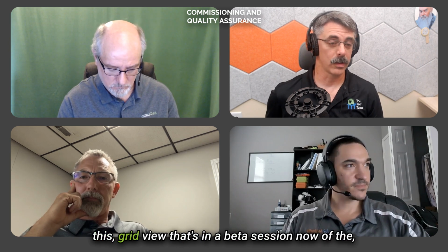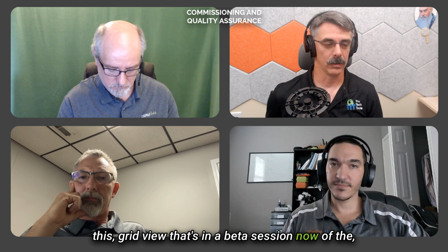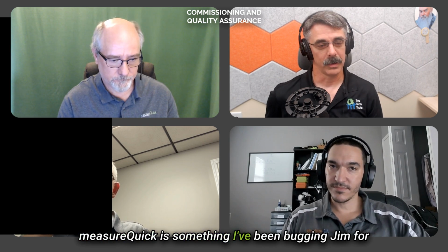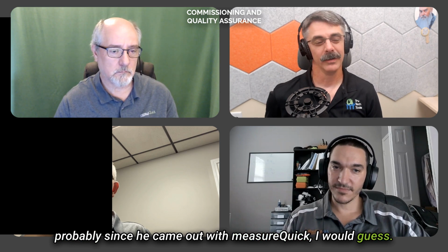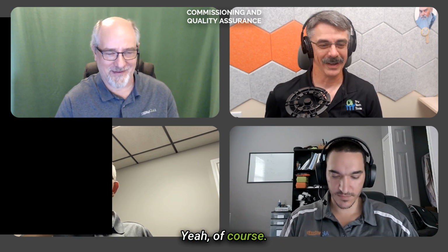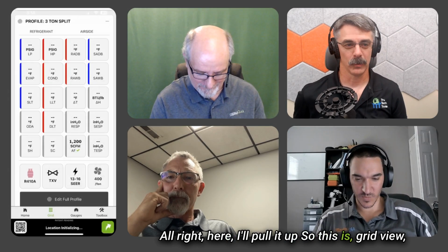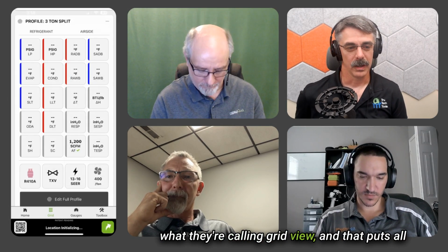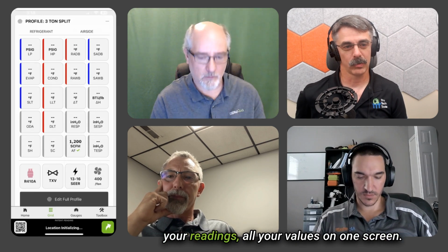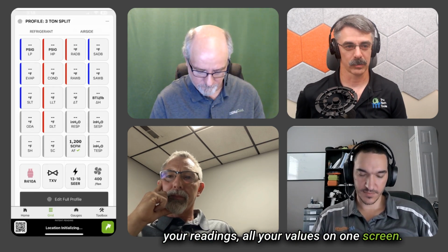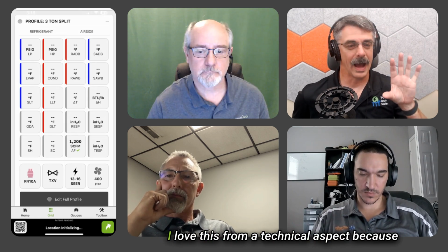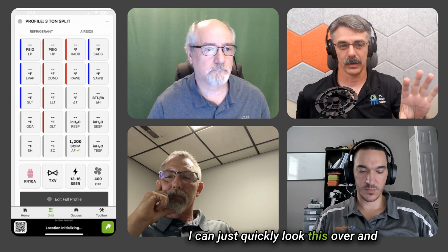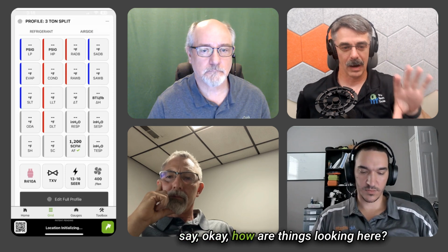This grid view that's in a beta session now of the measureQuick is something I've been bugging Jim for probably since he came out with measureQuick, I would guess. You got to pull that up, Joe, or you want me to pull one up? Yeah, of course. All right, here, I'll pull it up. So this is grid view, what they're calling grid view, and that puts all your readings, all your values on one screen. So you got your refrigerant on the left, your air side on the right. I love this from a technical aspect because I can just quickly look this over and say, okay, how are things looking here?